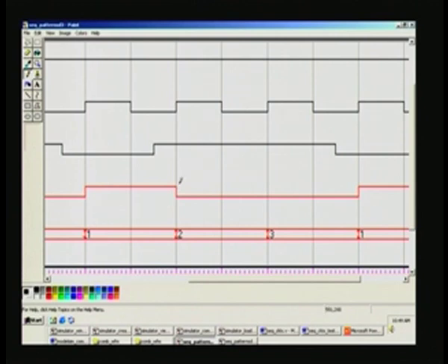So, that is what it is. If it is 1, what happens? From 1 to 2 it has gone. In 2, now again the 0 1 1 0 bit pattern has been encountered, that is why at the last 0 it goes 1 here. So, this is the corresponding output. So, whenever 0 1 1 0, even in a recurring fashion, you should have 1 here corresponding to that, and in state 2 we are analyzing, isn't it.